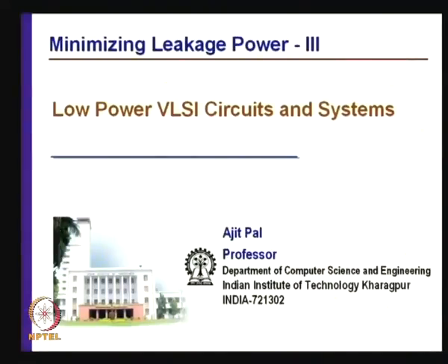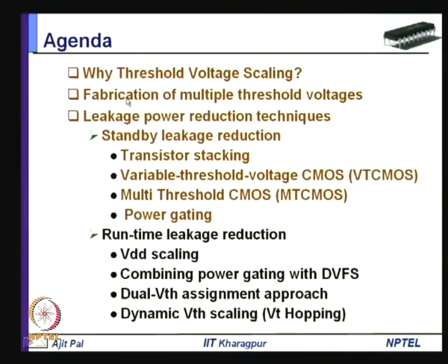Hello and welcome to today's lecture on minimizing leakage power. This is the third lecture on this topic. In the earlier two lectures, we have discussed various issues related to leakage power reduction, and we have discussed various techniques such as transistor stacking, variable threshold voltage CMOS, VT CMOS in short, multi threshold voltage CMOS, MT CMOS and power gating in the last couple of lectures.